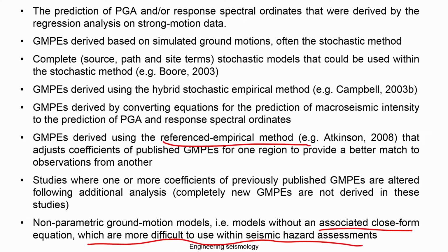The easiest thing to predict is earthquake hazard. So earthquake hazard in terms of earthquake parameters like intensity you can predict, duration you can predict, ground motion parameters PGV, PGD, PGA you can predict, and spectral parameters and Arias intensity you can predict if you have your predictive equation. So the development of predictive equations is very important for getting a reliable hazard prediction of a particular region.